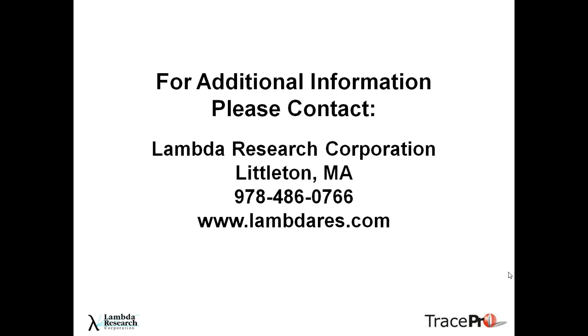Of course, with the binary format, you do have that problem. You can't read the file. But usually with normal DAT or TXT files, you can read those files and ascertain if they're correct or not. And sometimes just changing the header will make those files available to be used. Okay, well, that's a good point. So if you can find a sample or use the slides in here that show the TracePro Ray file format, if you have to modify that header, you can go right ahead and do that and see if that'll work. Dave, we have another question here.